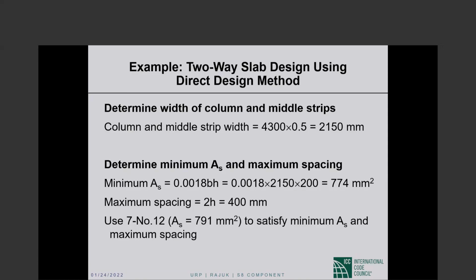Now the minimum flexural reinforcement and the maximum spacing. Minimum flexural reinforcement is the same as the shrinkage reinforcement for grade 480. It is 0.18% of gross.